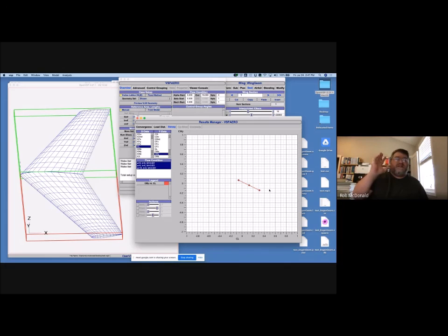And right, to design a wing and to get it all right, you've got to basically handle all these things at once. You need to figure out what speed you want to cruise at, what weight, and with what wing area. That gives you a target CL. And then you need to twist the wing or put in enough reflex so that you are trimmed at that point. And the slope of this line, here's another little trick. The slope of this line is actually your static margin. It's how stable you are. So this line in this CL, the slope of this line, if it's very, very shallow, it's less stable. If it's a horizontal line, it's neutrally stable. And if it's sloping up and to the right, then you have an unstable airplane.